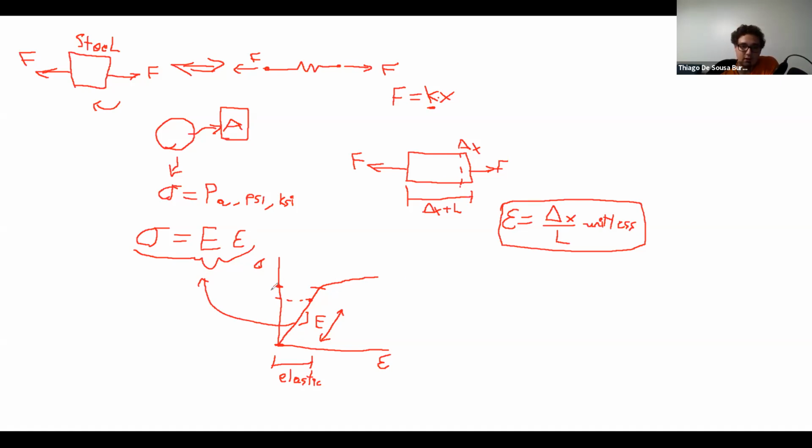I'll keep applying a stress, and what this graph is telling me is that I'm not applying that much more stress, but my part is deforming significantly. I have a video later on that will show this. And it will come to a point where it will simply break. In testing, it will just come back down to zero, because now the part can't resist anything anymore. This is the case for steel.